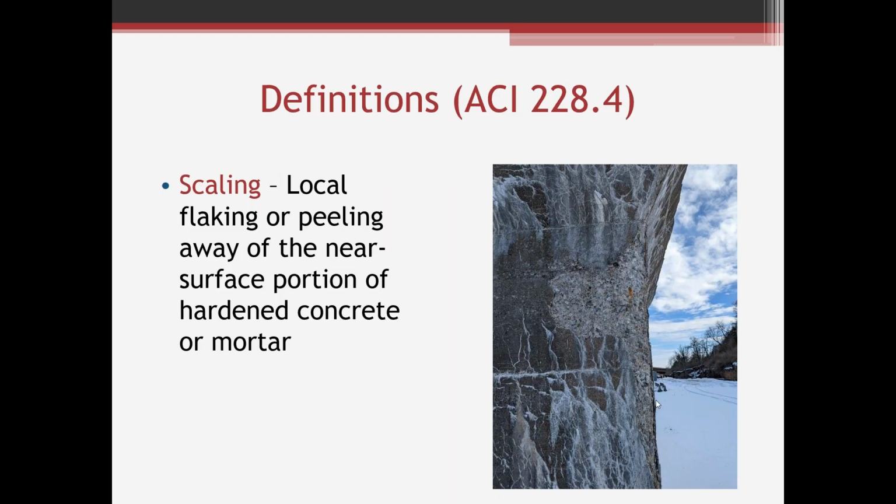If more starts to come off, like coarse aggregate, I'd probably call it more of a spall than scaling. But this picture here shows what I would consider to be scaling, probably due to freeze-thaw distress.